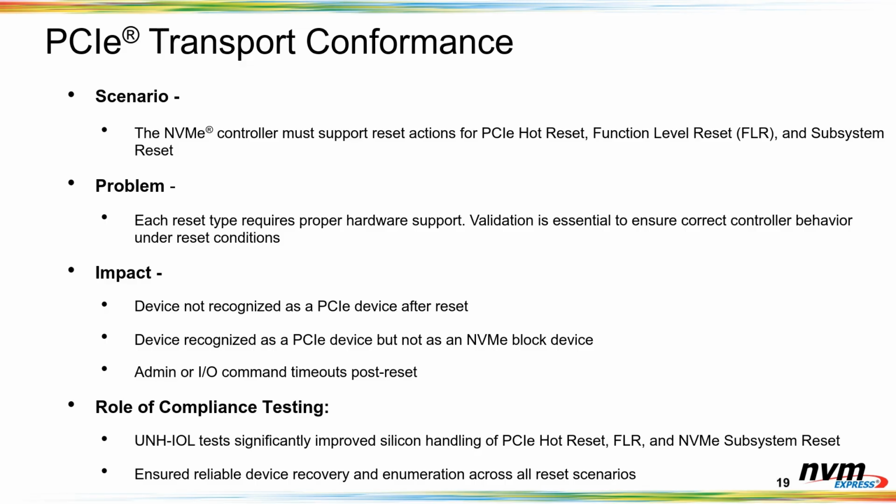The fallout or the impact of this is, the device is not recognized as a PCIe device after reset, or it's recognized as PCIe but not as an NVMe block, and admin or IO command timeouts post reset.